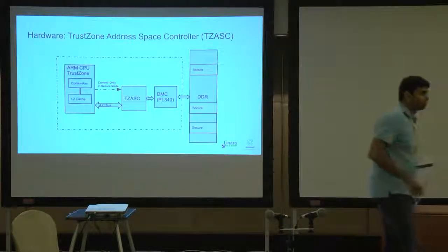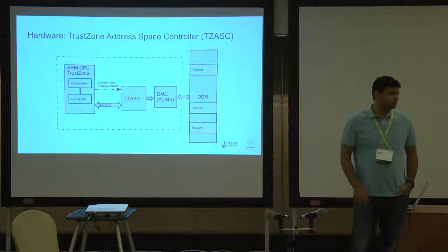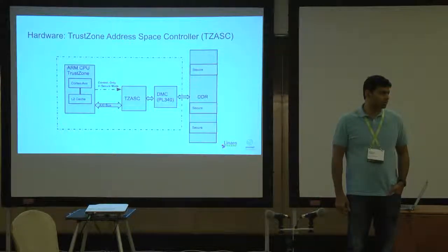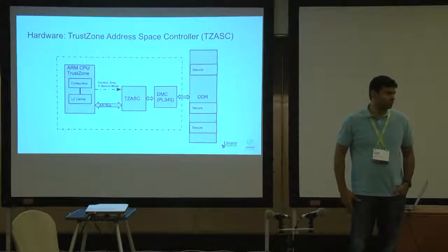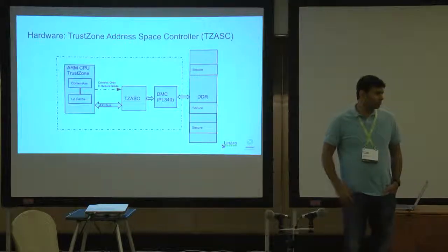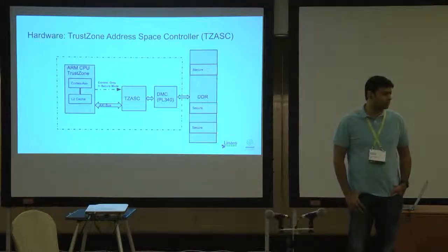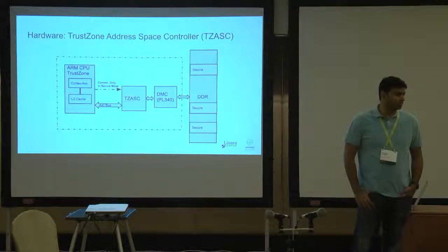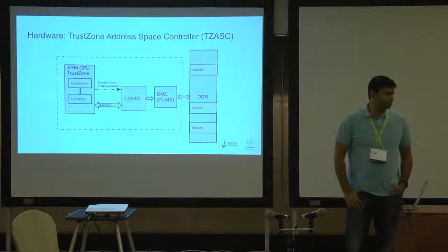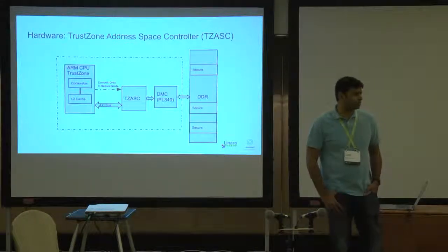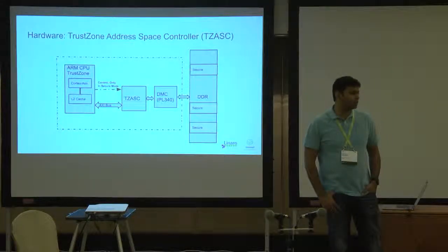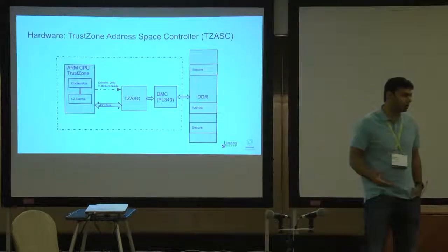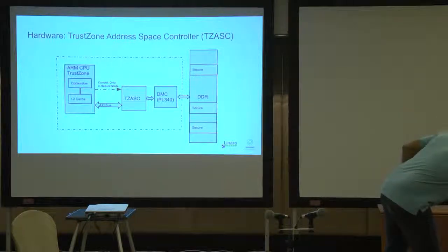I'm not necessarily an expert on it, but I know at least one implementation of secure playback was changing at runtime whether some memory area was protected or not through secure monitor calls into TrustZone. So only in the TrustZone environment can you change that, but it's runtime changeable, right? If you look at the TrustZone address space controller, it is programmable at runtime.